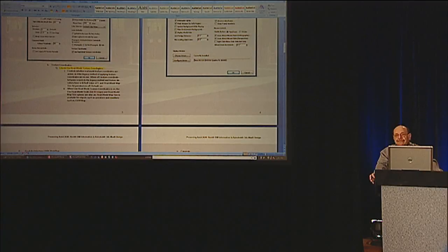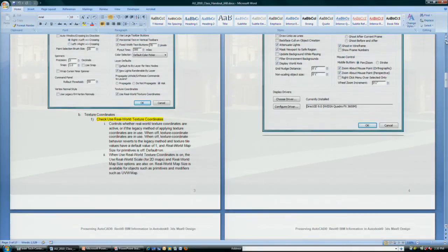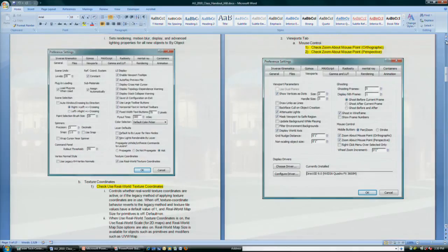So that was also fixed in the 2011.3, and it works very well now. So now you're getting FBM directories built underneath your FBX directory, and it's holding all the information properly the way it should. So that was a couple of the pieces that I wanted to go over, was how I was fixing that, but Autodesk fixed it for us. Isn't that nice?